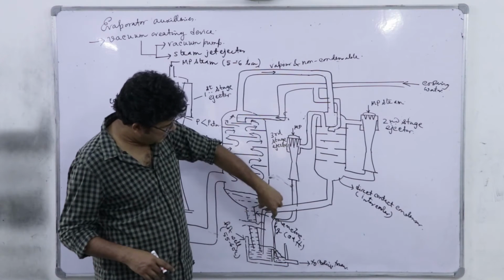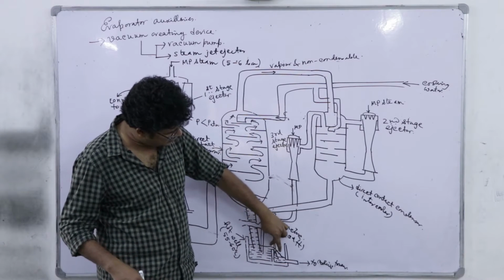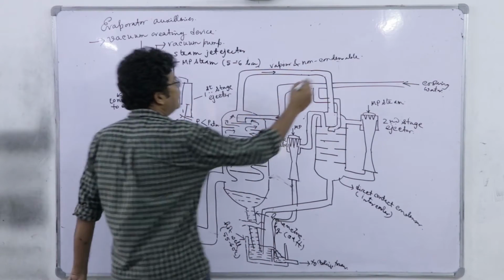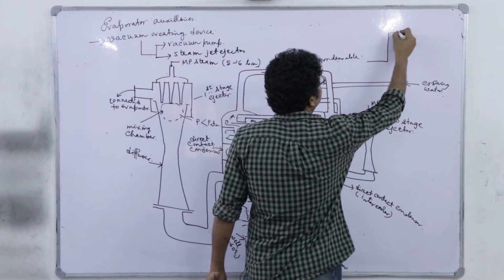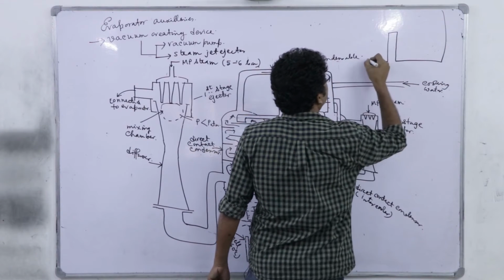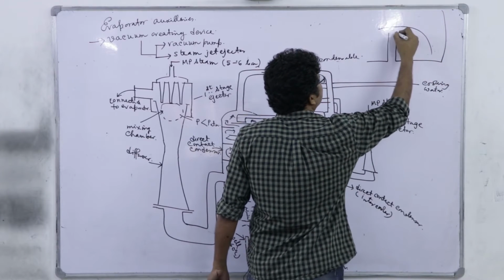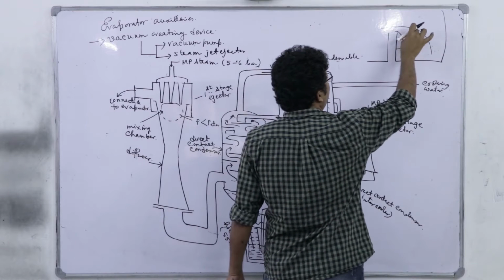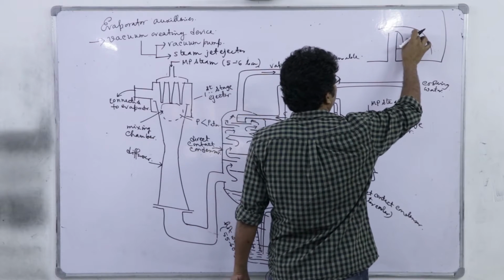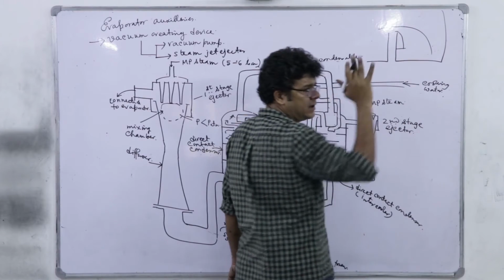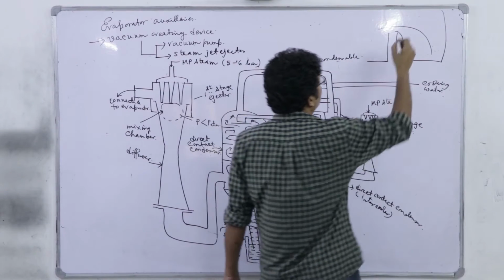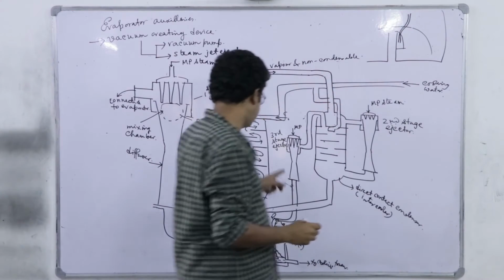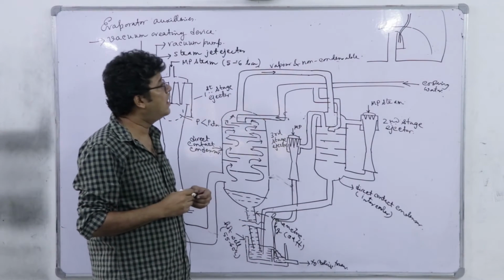actually you see that when the condensate is being released, this will overflow from first chamber to the second chamber. And if you look into the detail, what is the structure of this overflow? There is the partitioning wall, right. So as it overflows, it creates a space which is being covered from this side by the jet of water, and on these two other sides there will be the solid wall, right. And in this space we are discharging the outlet of the third or the last stage of this condenser.